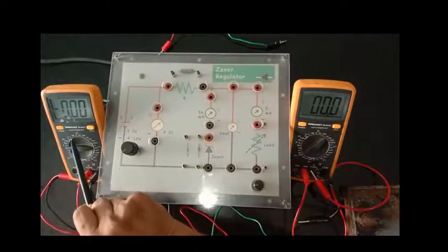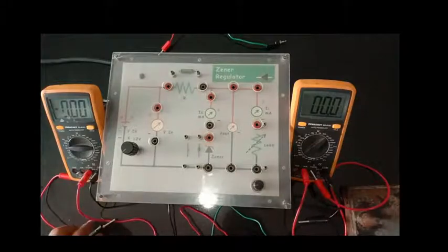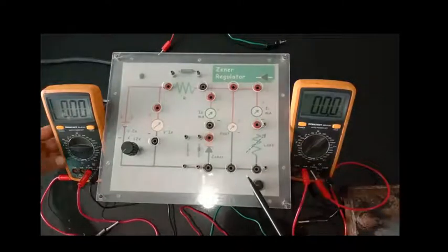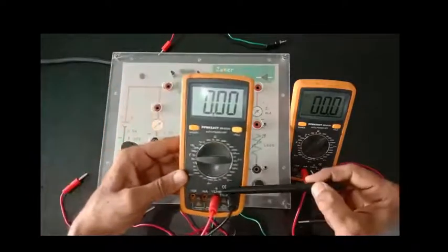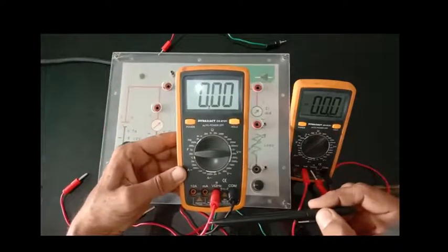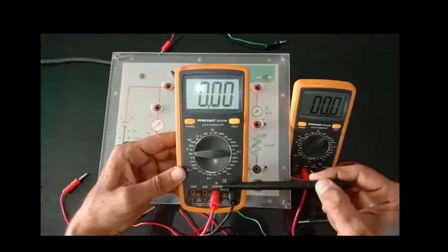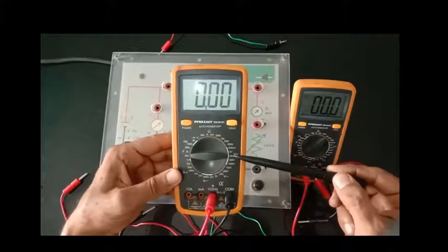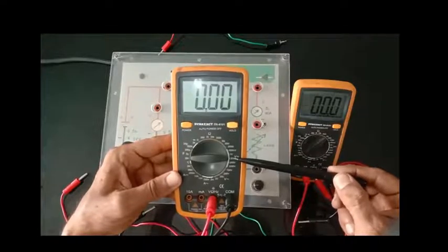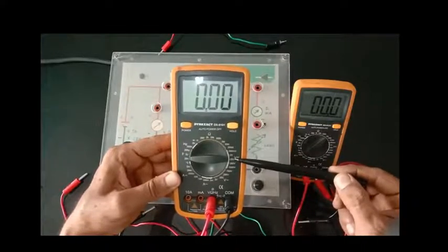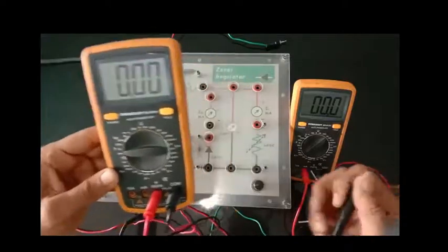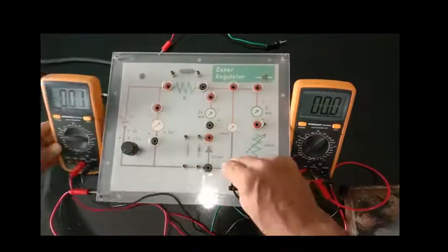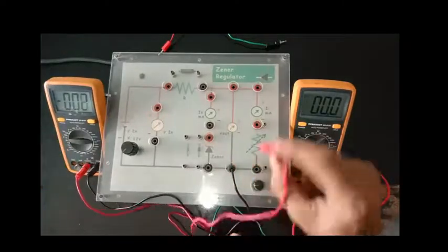The voltmeter should be connected at V out, positive and negative. The voltmeter will be set on volts, with the positive terminal on V and the ground as common. The pointer will be kept at around 20 volts, because the input battery is around 12 volts. So let us connect this one, the black to the ground and the red as V out.